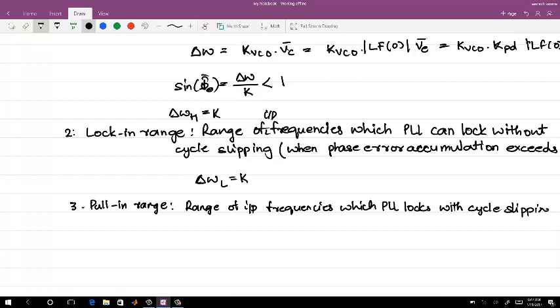So it is not easy to understand this with this PLL type 1 architecture, because here it locks within one cycle where the phase error accumulates to 2 pi, otherwise it doesn't lock at all. Now there will be kinds of PLLs where you accumulate a phase error of 2 pi, you have not yet developed the voltage, so you again develop more voltage.